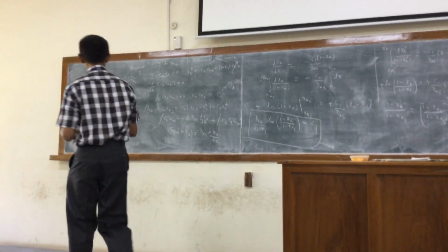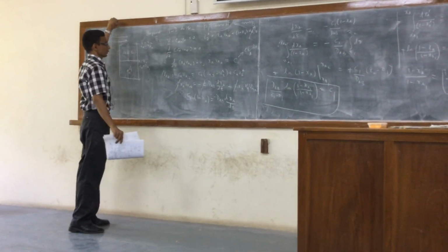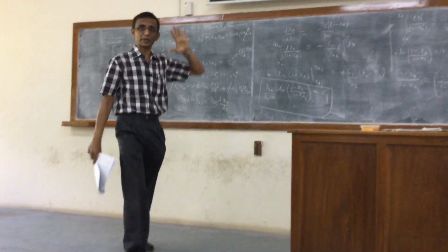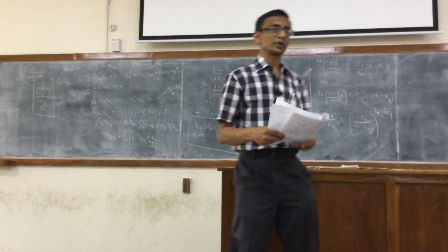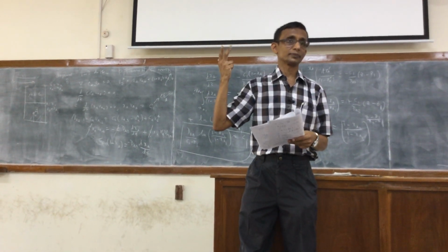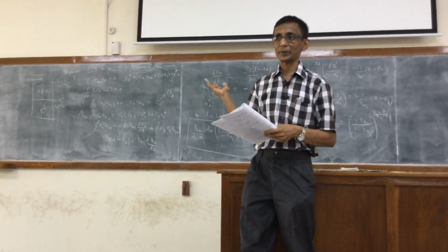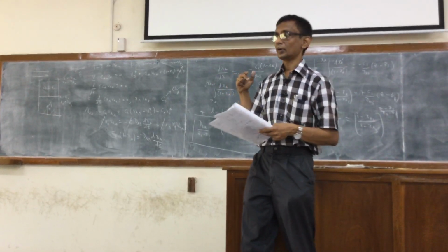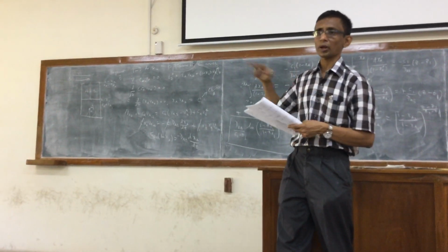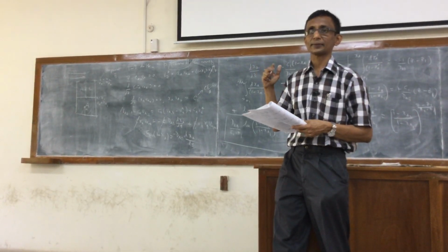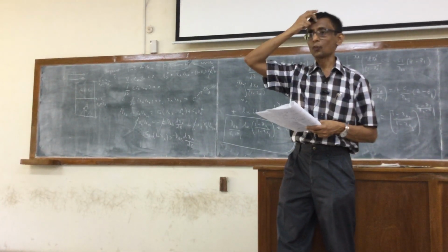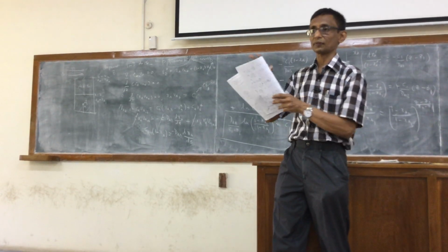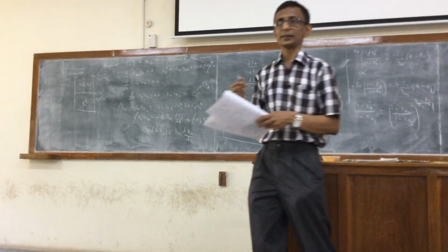It's a problem. That itself shows that it's a problem because VAZ is actually becoming very large. So when XA is 0, it is really not applicable right at the top. This is one of the limitations of the simple one-dimensional model. The basic problem is we are assuming that B is stagnant, and also one-dimensional. If you don't do that, then you get other terms in the continuity equation that will balance this. Clearly what he is saying is very true.